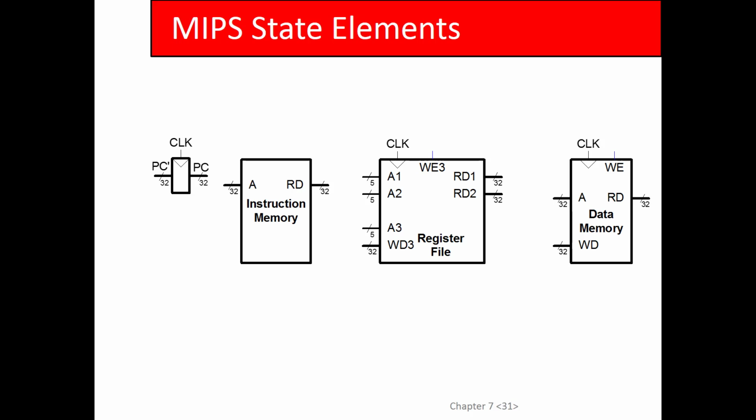The fact that there are 2 physical memories here is because we're going to do a single cycle CPU. In order to fetch the instruction and possibly also do a load or store, you essentially need 2 ports into your memory, and these guys actually represent the 2 ports.